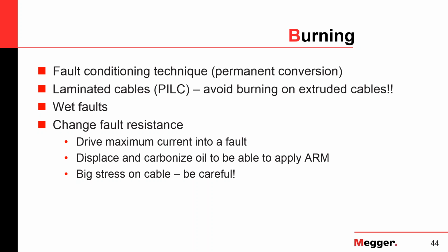So in most of the cases when people try to burn plastic cables, they literally burn it to death. They burn it open. They carbonize it into a condition where it's really hard then to go on with actual fault location. So be very careful with burning. It's a typical conditioning technique. You want a permanent conversion of your fault for laminated cables, not for extruded cables.